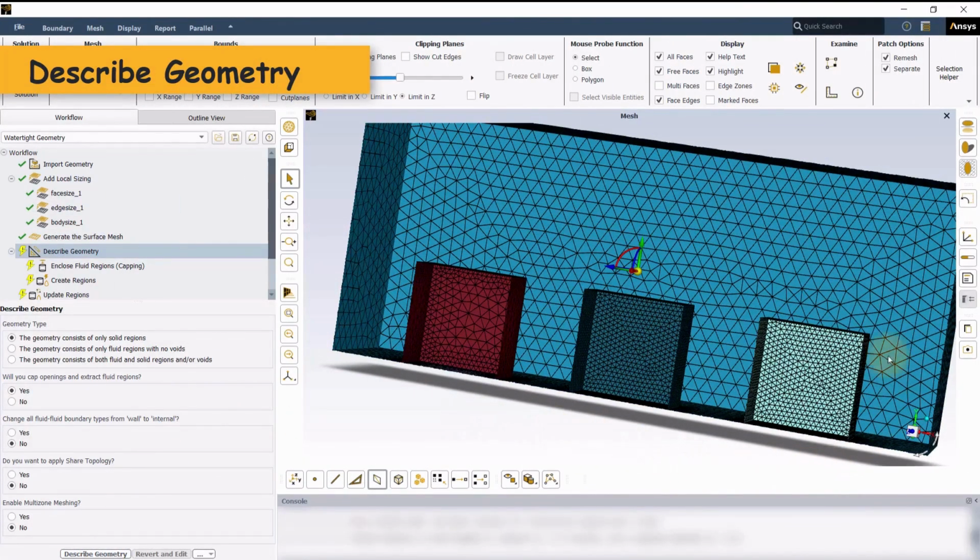Here is the surface mesh you should obtain. Body 1 shows a starkly different mesh distribution compared to body 2 and body 3. This is simply because the local sizing is specified only for the edges of this body. At the surface mesh level, the influence of both face and body sizing looks identical.